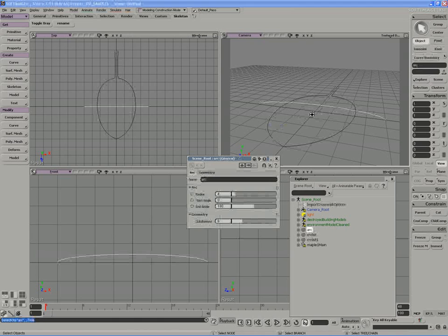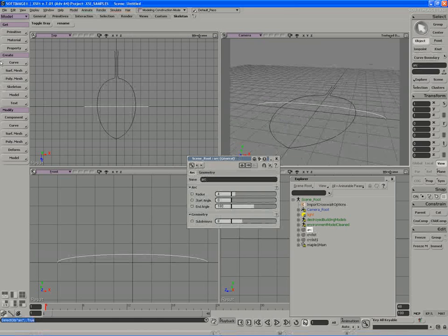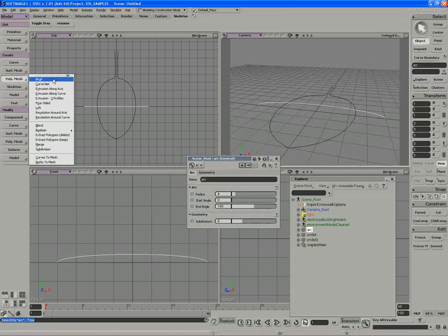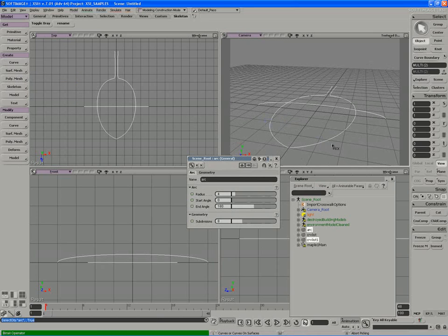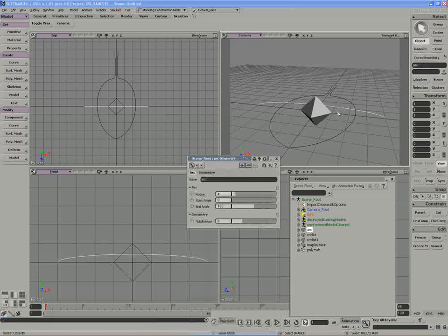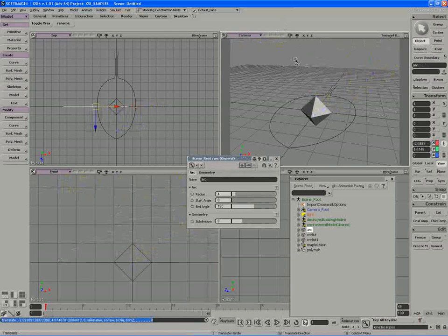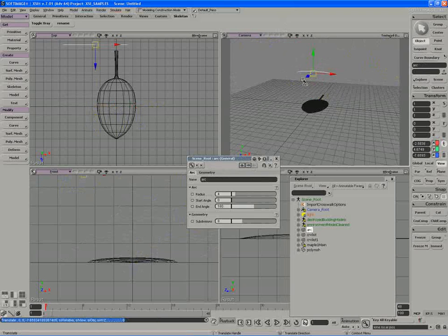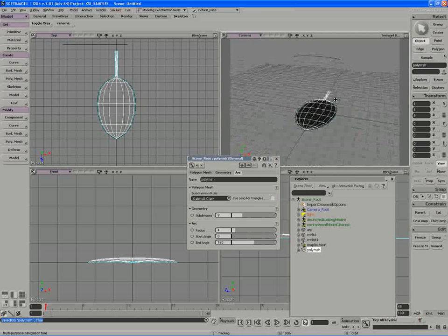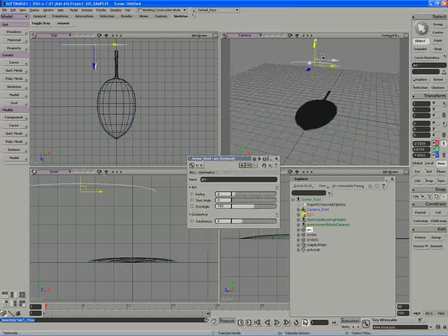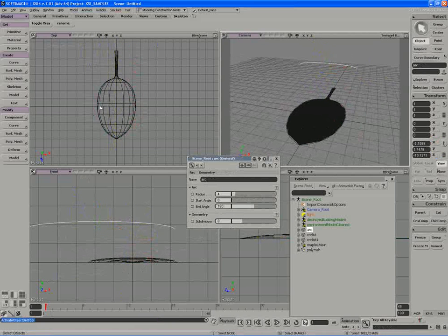Everything's good there. I'm going to start by selecting the curve and creating a brand new polymesh Birail from the 3. So the cross-section picked, I'll pick a left and a right cross-section. And sometimes you get this with the tool. Sometimes all it is a matter of just moving the cross-section. The Birail's kind of had this issue for quite some time now, where just moving the cross-section can dictate the shape that you get. Very weird, but it's still worth it. The Birail's a very nice tool to work with.